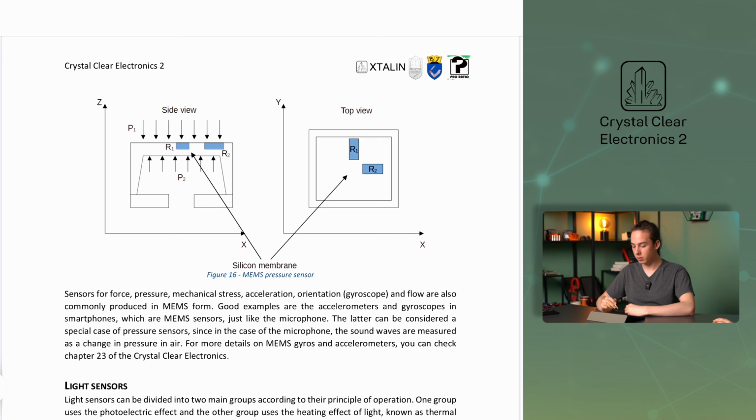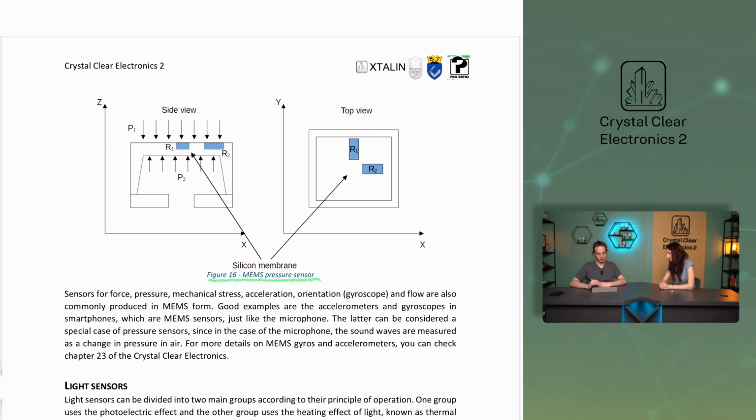As an example, the MEMS implementation of the pressure sensor, already discussed, is shown in these figures. The left figure shows a simplified cross-section of the sensor. Above is the diaphragm, below is the cavity in the sensor, and below this is the sensor housing and the aperture in it.